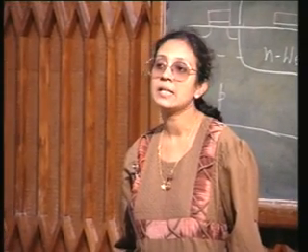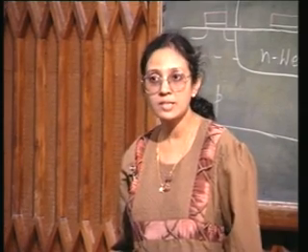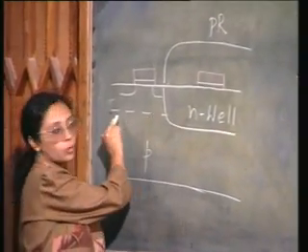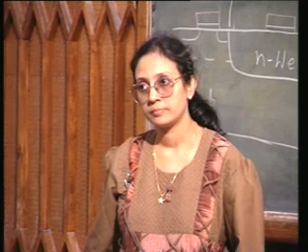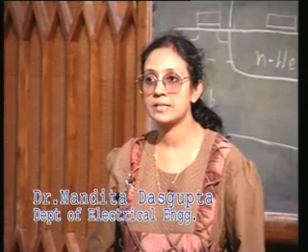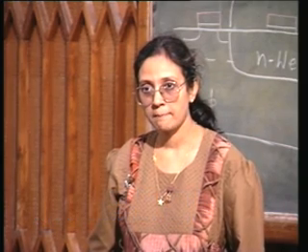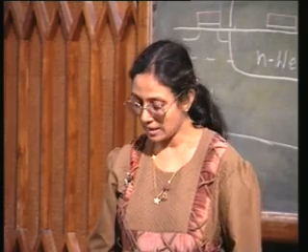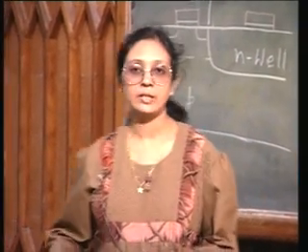So, essentially this technology is analogous to the Nwell technology. The only difference is in this additional boron implantation, which is helping to prevent subsurface punch through. So, this is an example of the secondary Nwell twin tub. This is not a true Twinwell technology. This is a secondary Nwell technology. Okay. Now, let us come to a true Twinwell technology.